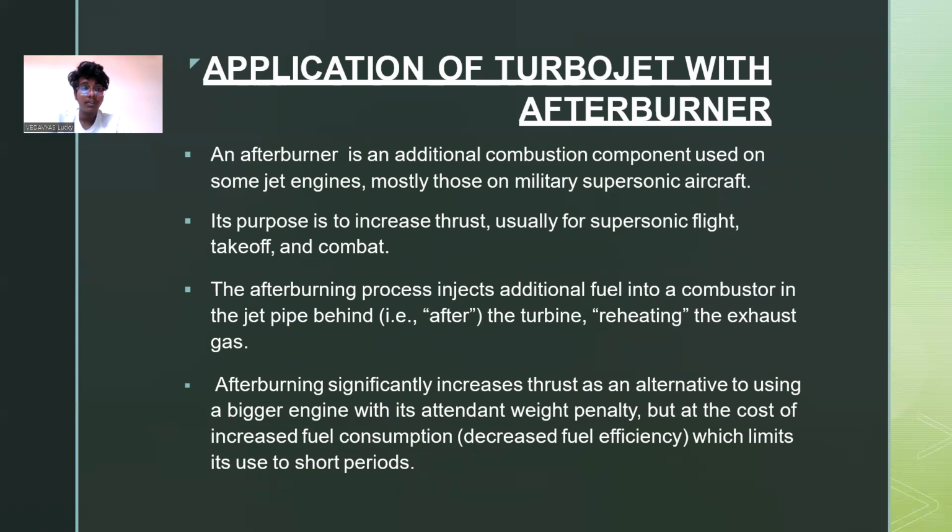We cannot use the afterburner for longer periods because it takes up more fuel and has less fuel efficiency, and the range and endurance of an aircraft will also decrease. So we turn on the afterburner at the initial stages of flight. After coming into cruise, we have to turn off the afterburner so that we are able to save some fuel at supersonic flight.